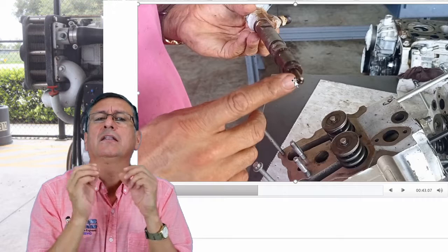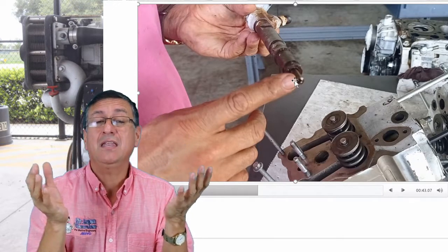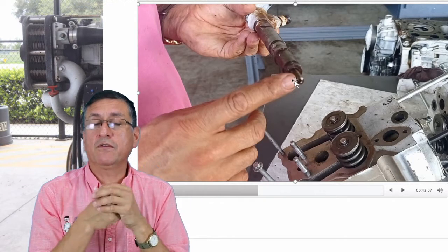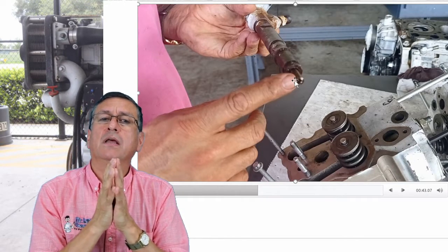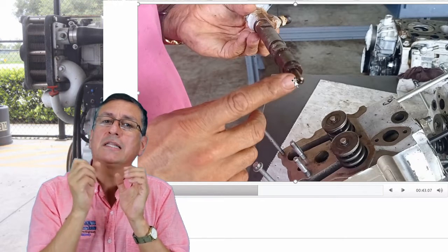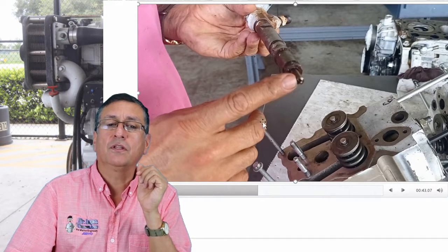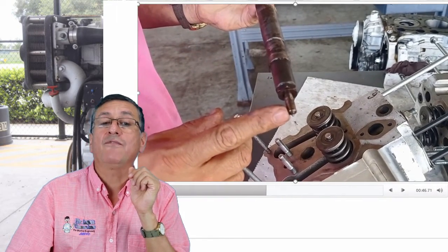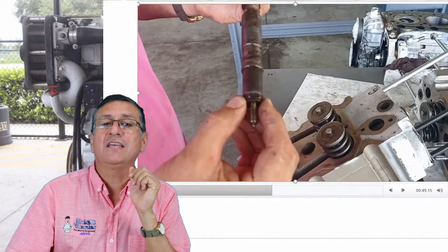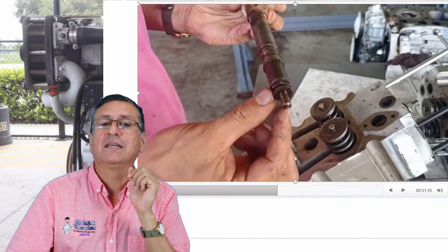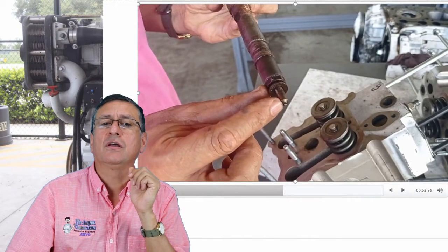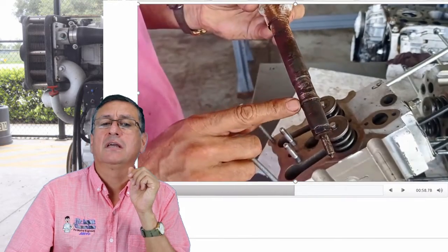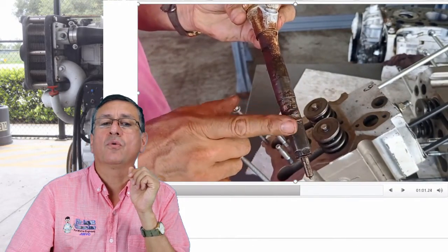It's not complicated. The only thing that you need, once again, is the parts manual and the service manual, both of them. And if you have the parts manual, probably you have the part number and you can order the kit. I have an example in this video. Okay, check the nozzle, and be careful with the washer. This is the copper washer, correct? This is the copper washer, and the nozzle, verify the condition, and special washers, and this is the O-ring.